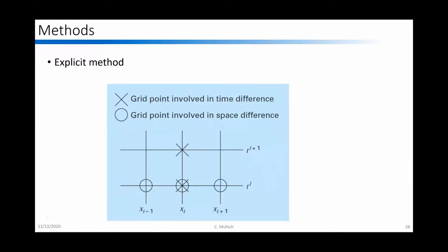So what we're going to do is zoom in. I've zoomed in here on some different nodes. So here are my different x's going across this way. Here are my times going up here. We're going to talk about the explicit method. So we're going to solve using these different points. These x's are going to be my grid points where I'm going to solve for my time difference.